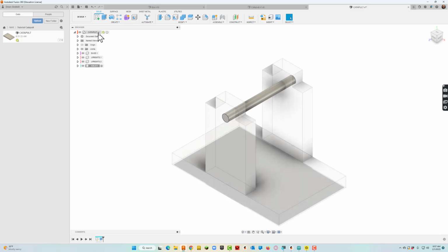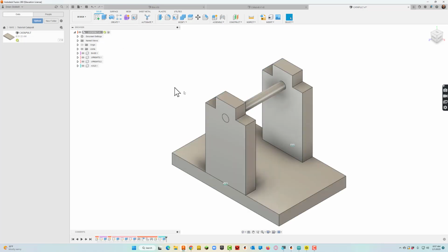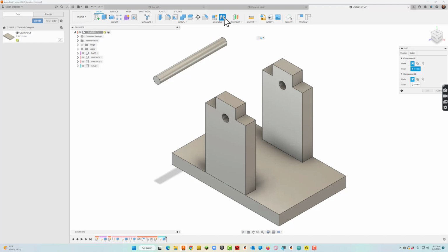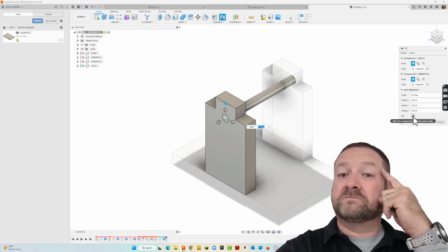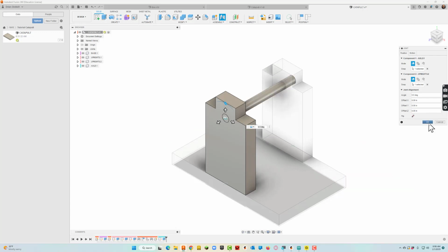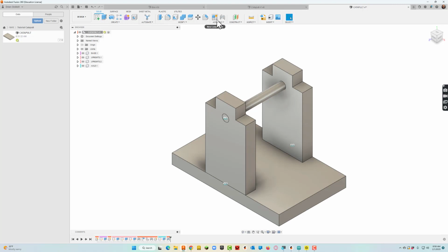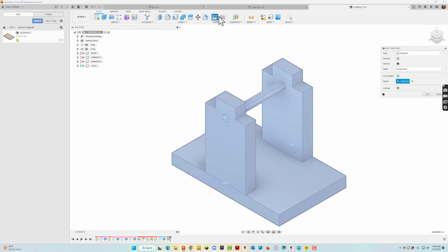I'm going to go back out here, get to the entire assembly. Now remember, that's not jointed just yet. So I'm going to go over here to joints. Click there and click here. Now remember, here's the flip button. Just in case it gets all goofy on me, I can hit flip. It may come in like that to begin with. I'm going to go ahead and create the lever now. So make sure I've got catapult selected. Hit new component. And I'll call this the lever.